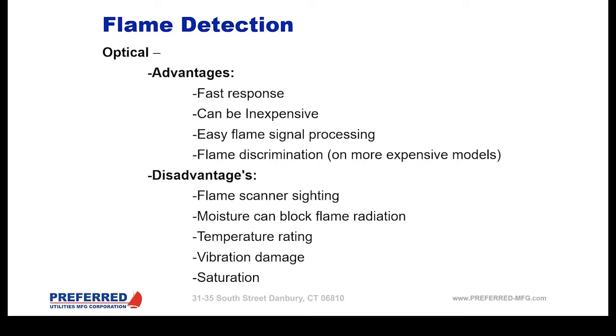And what I mean by that is, for many, many years in the industry, infrared was kind of looked at as it sees refractory, that scares us. Well, as electronics have gotten better and more complicated, if you will, most of the flame safeguards can recognize the difference between the actual combustion or burner infrared radiation versus the refractory radiation. And that was the biggest scare for that type of sensing technology for a long time, because refractory tends to generate an infrared signal that is very slow modulating, whereas a burner infrared signal will be faster modulating. Therefore, we can discriminate between one versus the other.